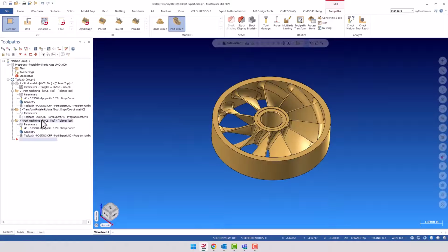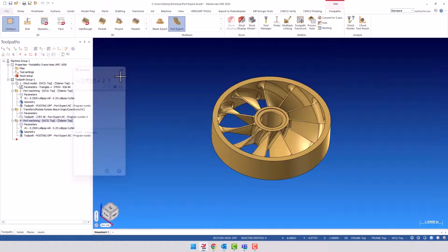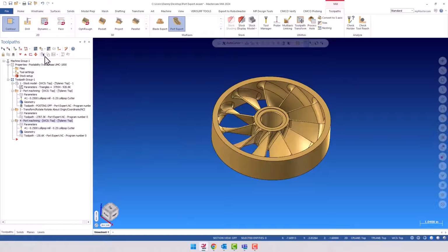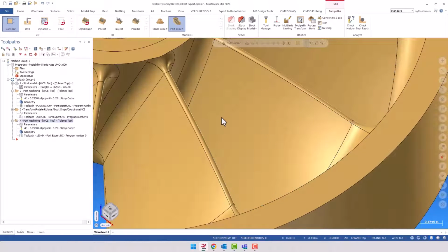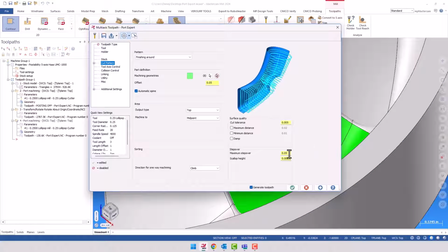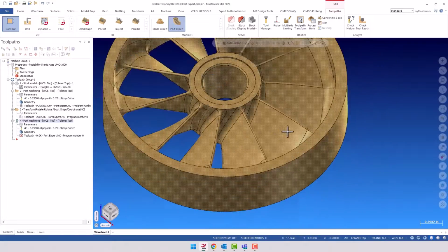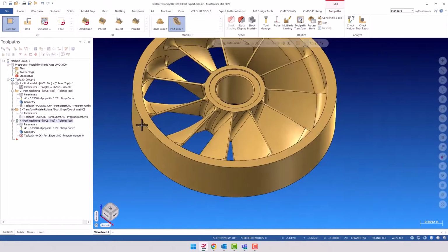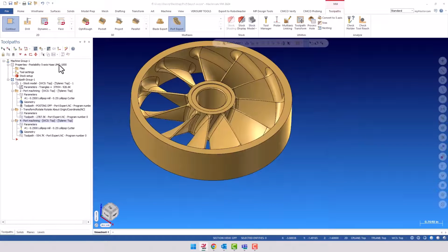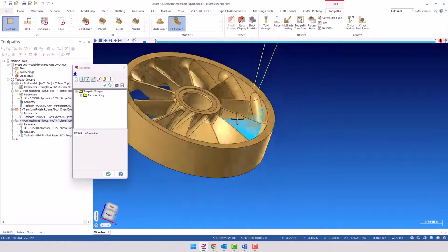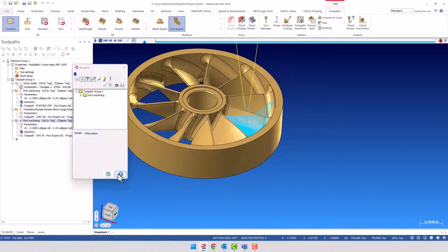Let me turn those toolpaths off, and then we backplot just this one. Oops, sorry. That one was ghosted up because I did the copy here. Backplot them. And now it's doing a little finish toolpath. I should probably lower that down a bit. My step over should probably be a little less, but we'll do 10 for the exercise and select OK. And then we'll backplot that. That's starting to look pretty good right there. I like it. Doing some ramping in up there.